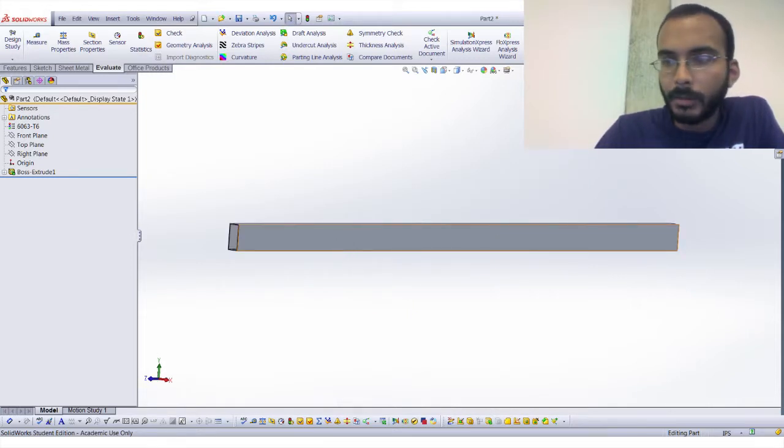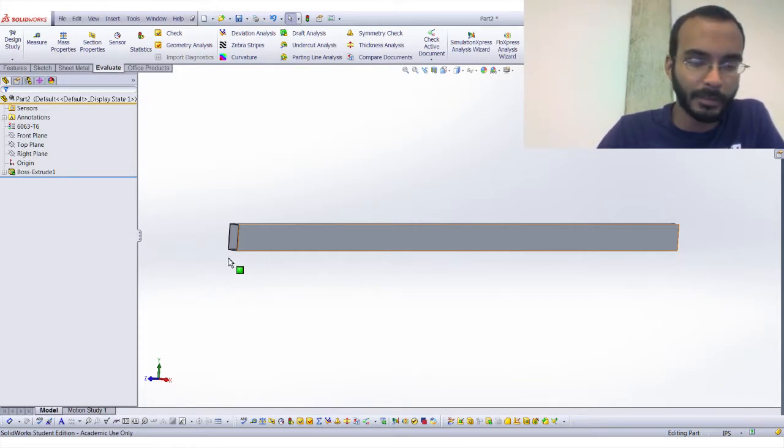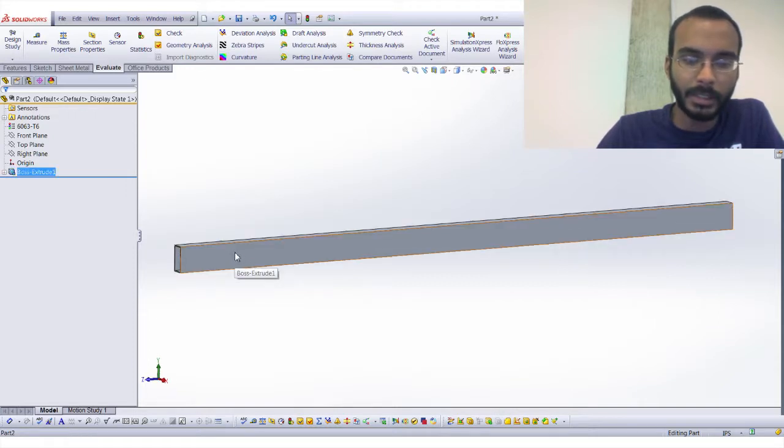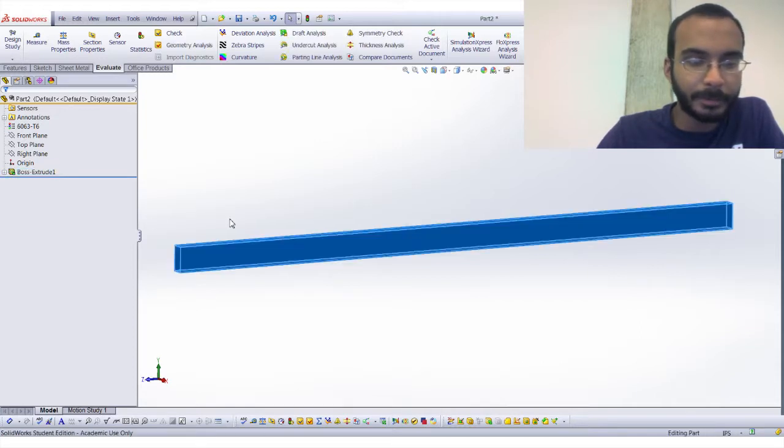All right, so now that we've sketched, it doesn't really matter where you do this. If you have just a plain rectangle, or if you have something like I have, it doesn't really matter. But if you right-click on one of those faces, it'll bring up your full right-click menu, which is where you can also start getting acquainted with as well. So SolidWorks likes to prevent you from having to move your mouse all the way to the top sometimes, so it gives you kind of suggested items here. So you can hide and show it. So if you want it to go away, you can hide it. Now it's gone. Then you have to come back over here and hit the glasses again to show it.